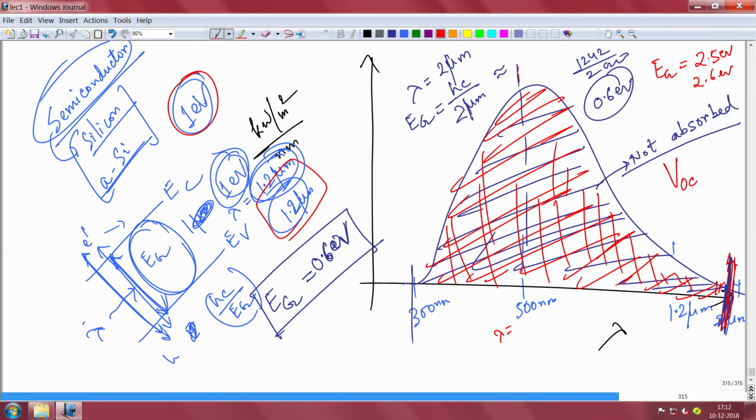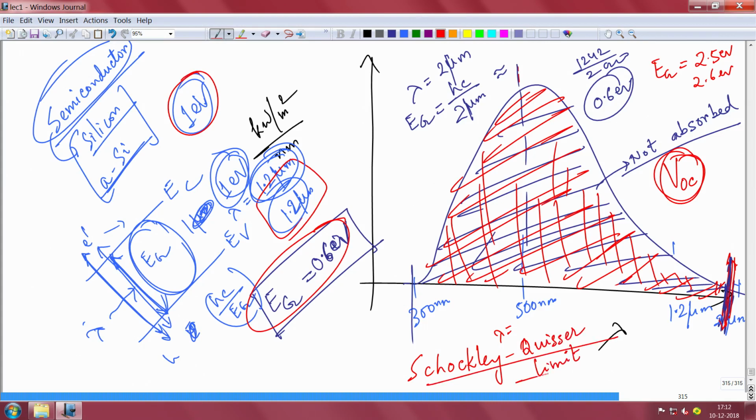and that open circuit voltage is a measure of how much voltage you can drop across your load when you are using a solar cell, and you want that voltage drop to be large, okay, then only you will be able to draw higher power and get better efficiency. If you use a narrow band gap semiconductor, your open circuit voltage actually suffers, so your efficiency comes down. There is some very beautiful trade off, okay, it's called the Shockley-Queisser limit, and that's something we have to discuss in one of these lectures now. You cannot arbitrarily have a small band gap material, it will not lead to an efficient solar cell, that is what is meant, okay. So, those are design things, we will come to that, okay.